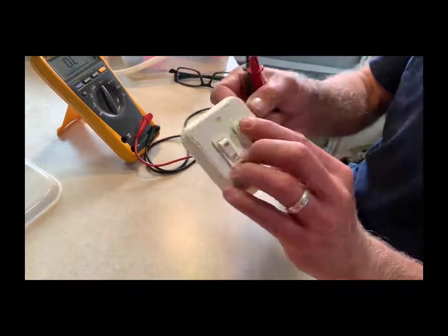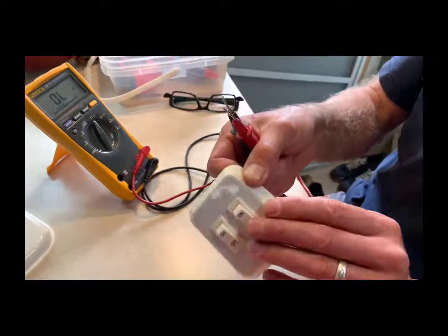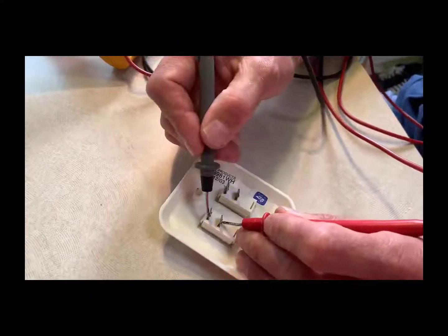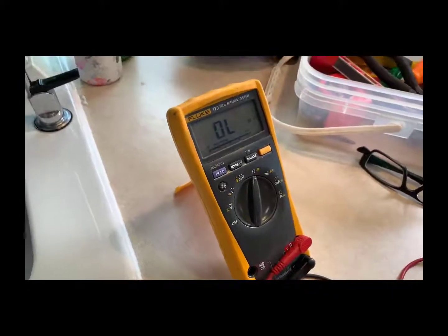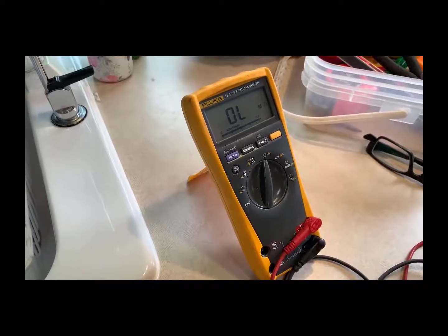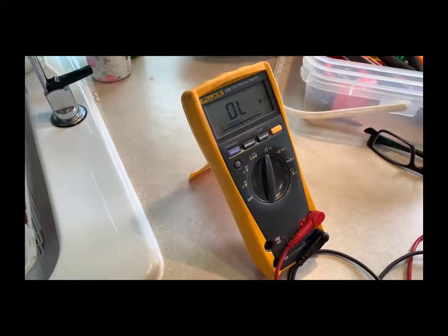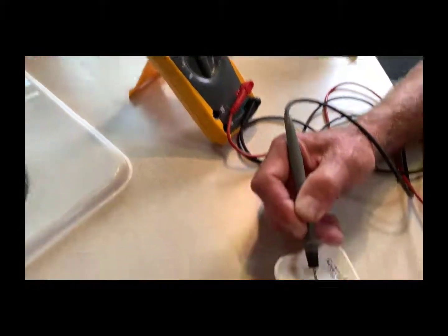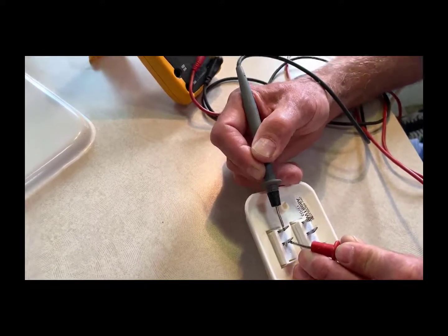So I'm just going to take this switch here on the right, and I'm going to first start with it in the off state. You can see it's clearly in the off state. Then I'm going to go to the two terminals of that switch and measure the resistance. If you look at the ohm meter right now, you can see it's measuring OL. From the lab, we know that means it's reading greater than what that ohm meter can read, and that ohm meter can read up to 10 mega ohms, or 10 million ohms. So what it's saying is we have an open circuit value. So we have 0 current flow for an open circuit value because the switch is in its off state.